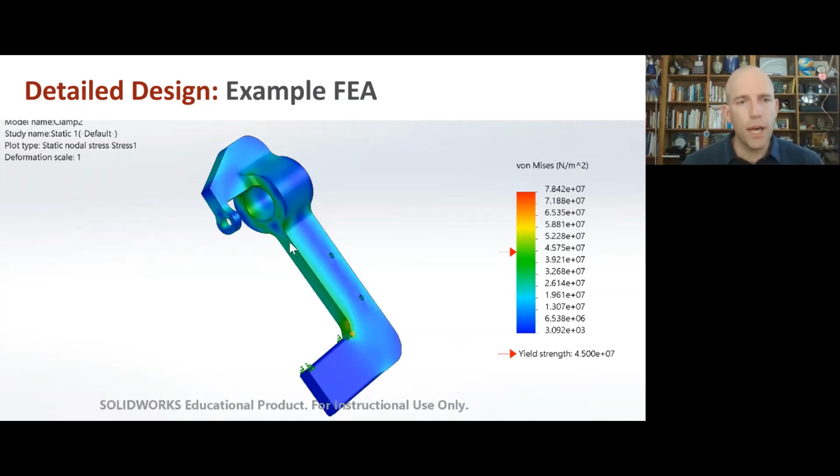And you can see, as we expected, we've got really high tension on the innermost surface, and then sort of a bending pattern. There's still some compression on the other side. For this cross section, I roughed it in using back-of-the-envelope analysis to get some of the parameters, and then iterated in finite element analysis to get some of these details, like the thickness of this bypass. This introduces some interesting stress concentrations because you need the drive shaft to be able to get through here, and you need that drive shaft to have a pretty big radius to avoid failure due to torsion and shear, given the layer alignment from the print job.